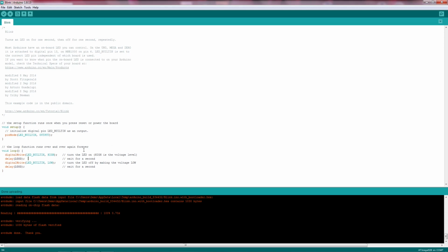And that number is then used to calculate, for example, for millis and delay, there's a timer, and it calculates how many cycles the timer should run before it basically notifies you, you being the Arduino libraries, that a millisecond has passed. Right? So if you have 1,000 here in a delay, that means there's gonna be 1,000 such notifications. It's roughly like that it works.